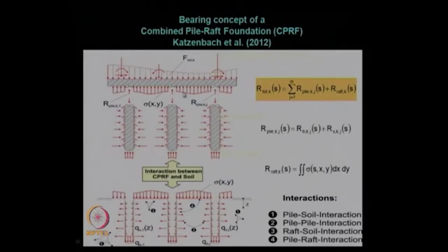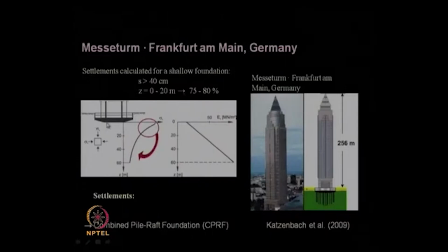So, with the combined piled raft foundation, as I was mentioning, a raft alone is not possible because it gives us a huge amount of settlement. So, to reduce the settlement you should go for a deep foundation, which is a pile foundation. The problem is it will be very costly, because when you are using more piles it will be costly. So, somewhat of an in-between solution is always this combined piled raft, if your soil profile and site condition is preferable.